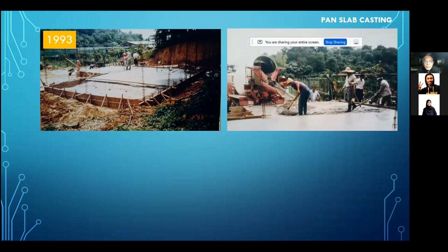First I created the formwork for the beam, for the slab, and I used a rough foundation. There is no reinforcement other than this welded fabric. It was not shown then, and I showed the other slide. It's laid there as a rough foundation. And then I called in the concrete mixer. We poured the slab together, and it took not even half a day, about 3 or 4 hours to complete.